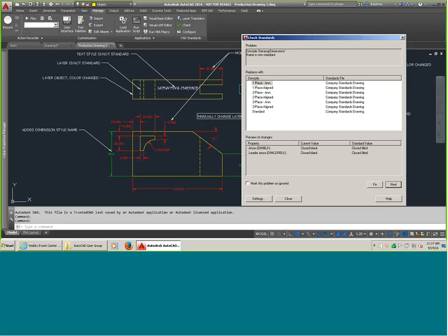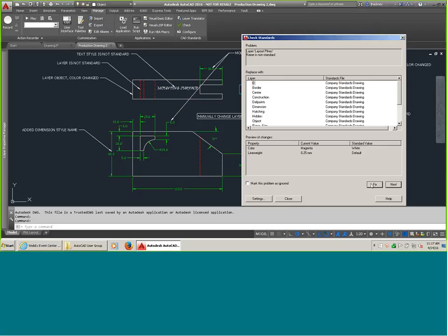So somebody had a general dimensions and it's supposed to be one place annotated. And here's the differences right here. So I'll go ahead and fix it. It also says that I have an object layer that was changed in color. There's the yellow. It should have been white. So I fix it, watch it change, and the screen updates. Now the dimensions haven't changed yet, but they will. Just keep an eye on them. They're a little slow getting started. There they go. They sometimes take a little bit because they have other properties that control them.